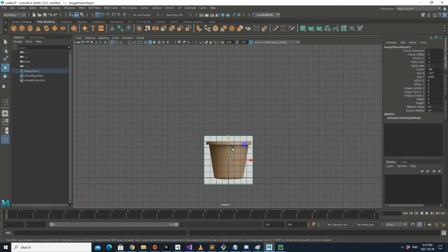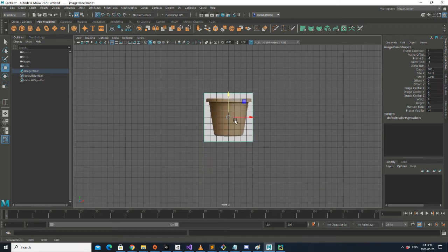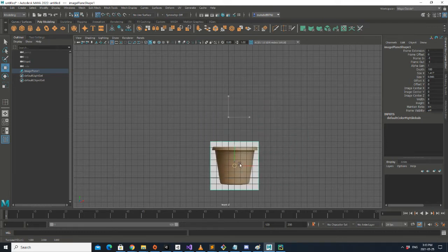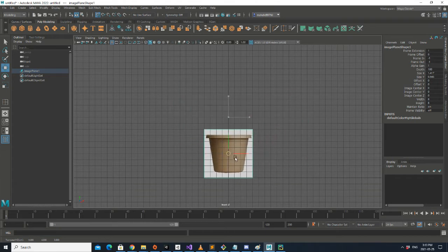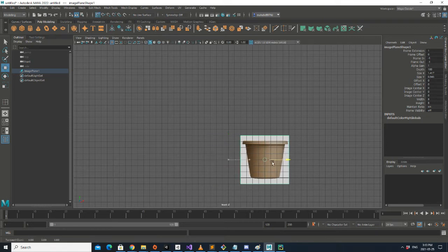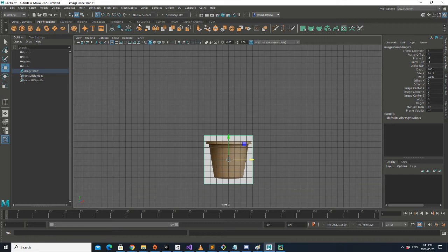So if you want to snap your model over these dots, press X, and then you can just move the center of your model over these predefined dots. For example, I think the best one for me is this place. And also you can just press this button to do it as well. They're exactly the same. Yeah, I think that's it. Any question?